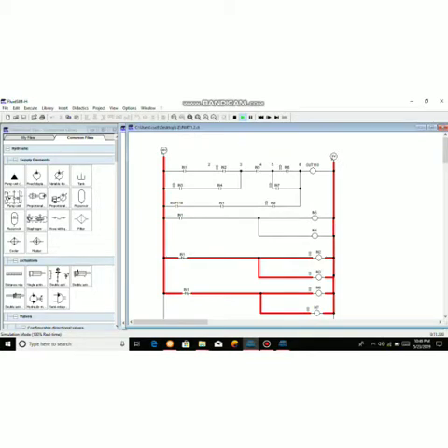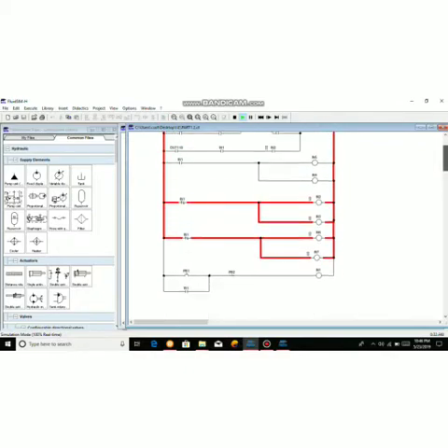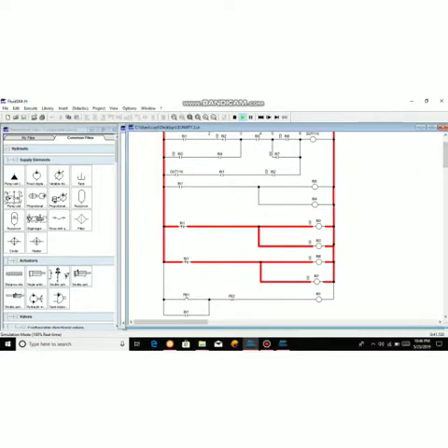For circuit 2, we can get two operations. Contact can interact when the circuit is running. Push button and relay are used so that the contact can be controlled when the circuit is running. Relay out can only function when IN 1 and IN 4 are energized. Therefore, the push buttons and relay that control IN 1 and IN 4 are only used to make the circuit operate.